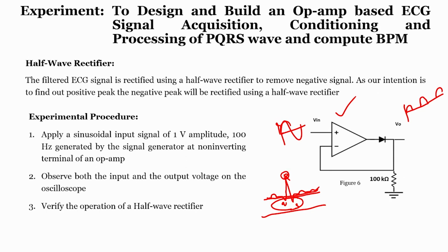The idea is that if I can set a threshold, if we recall what we discussed in the first session of our experiment, and if I can find the peaks, the number of peaks above this particular threshold completely gives us the number of peaks in a particular duration of time. But why do we have to consider this? The reason is, when we see the peak, this also will be considered as a peak, this also considered as a peak. So, if I do not consider the threshold, even these things can also be considered as peaks, and it is very hard to understand the BPM correctly and accurately.